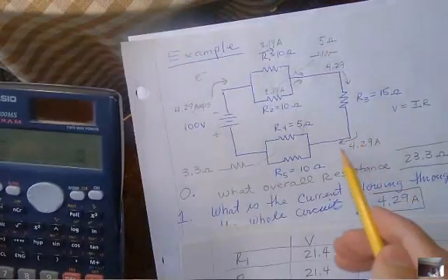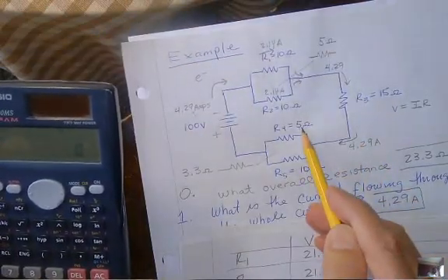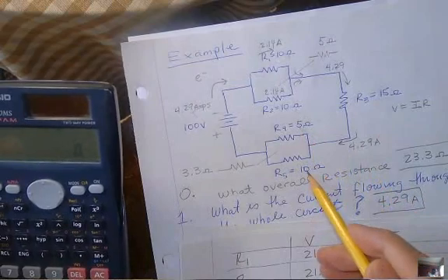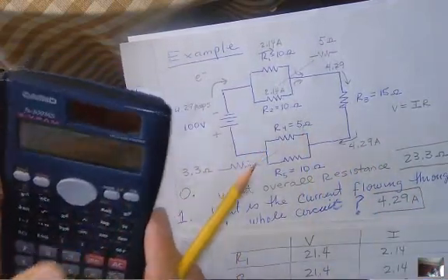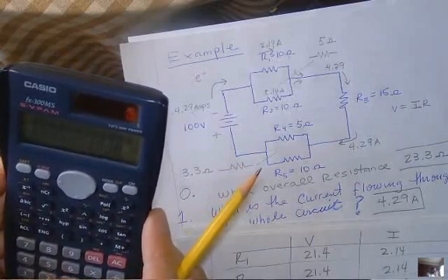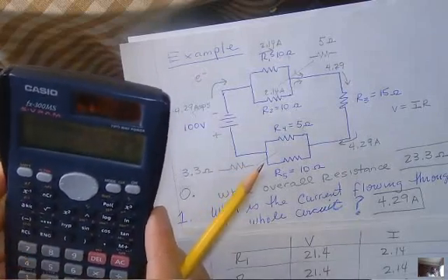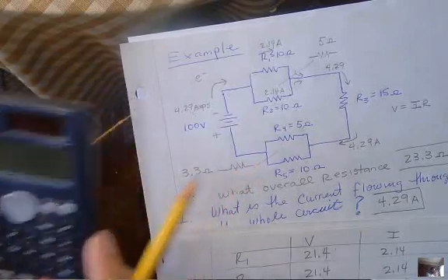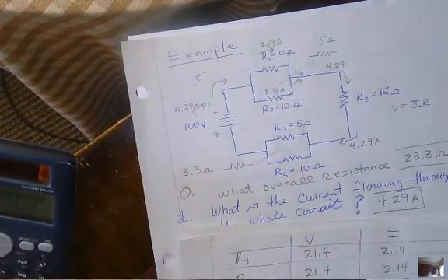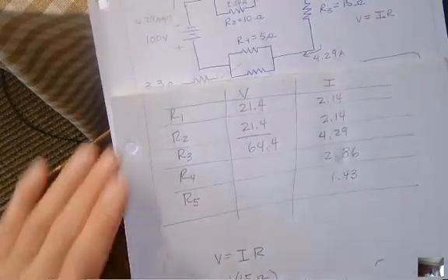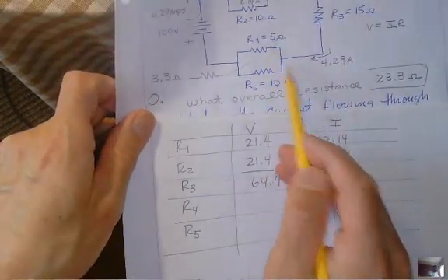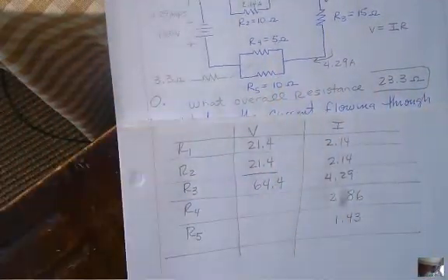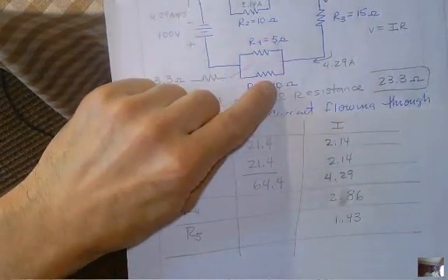So here comes all of it. This way is harder, twice as hard. So a lot less is going to go through. Most of it's going to go through that way. So let's take 1/3, 0.333 times 4.29. Okay, so 1.43 goes that way. Okay, so my partitioning is 2/3 go the easy way, 1/3 goes the hard way. All right, because this is twice as easy as that.